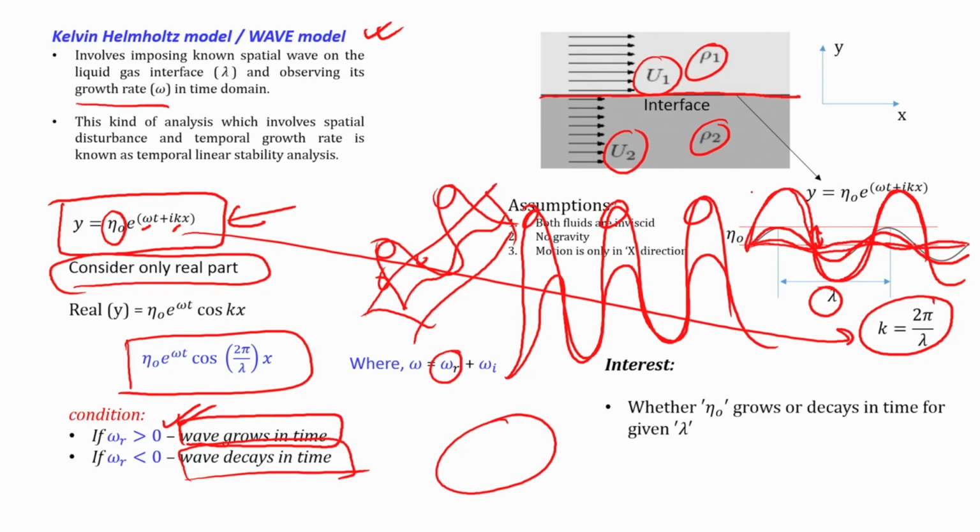So, the idea is to use a stability analysis to see what happens to the perturbation that you create on the surface of the sheet, which is an infinitesimal perturbation. This is the growth rate of those perturbations and this is the wavelength of that perturbation. The idea is to see whether the real part of the growth rate grows with time. If it does, that perturbation will aggravate and become something like this, otherwise it will attenuate. So, there are some criteria: not all wave numbers can grow, not all wavelengths can grow. Some wavelengths will grow, some will not, and that depends on the surface tension and a lot of other factors.